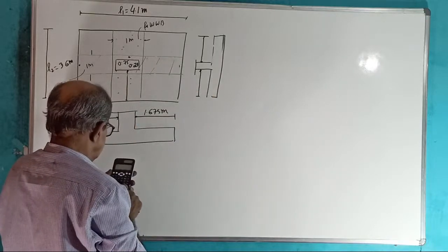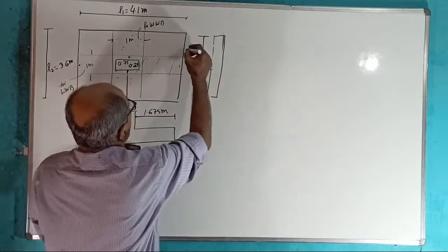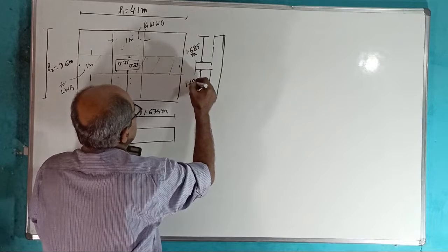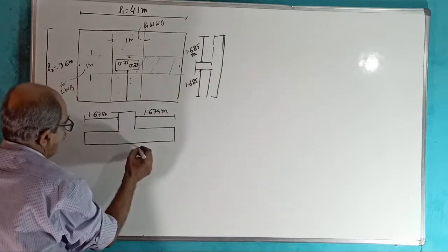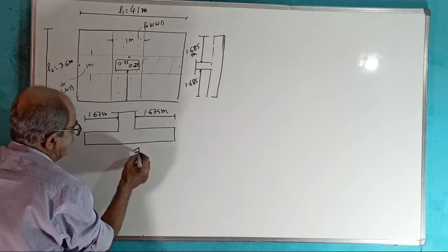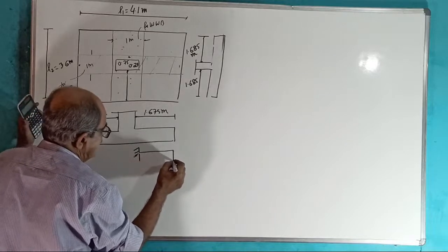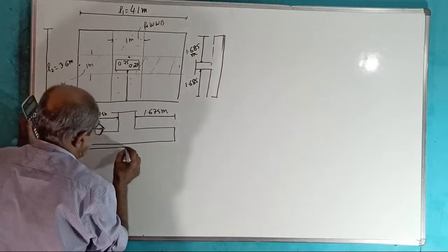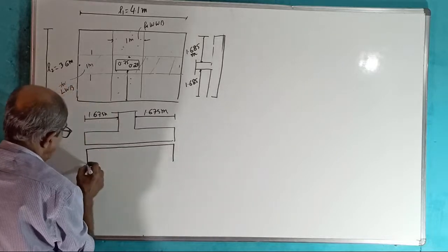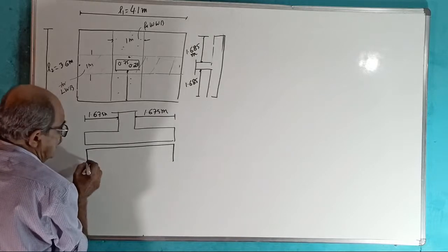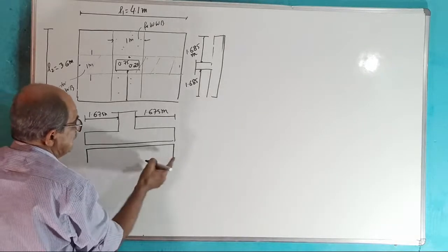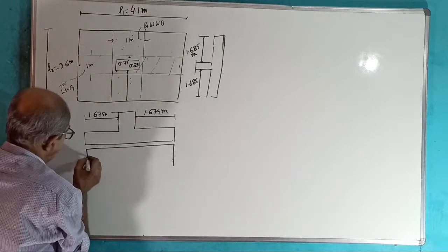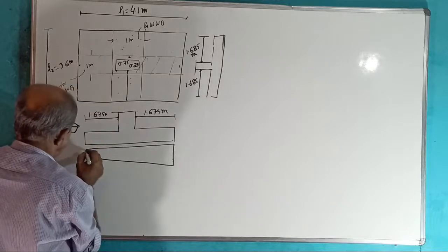Okay, now, at that time, this projection and these projections are 3.6 minus 0.23 divided by 2. Slightly changing. 1.685 meter. This also 1.685 meter. And for lengthwise projection, we took a cantilever here. And actually what I have done is, first I took the pressure diagram. I think pressure is more that side, correct? It was like this, out of scale. Okay. This was the pressure diagram.